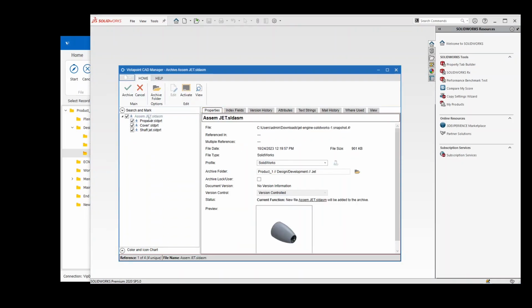Of course, it can read the SolidWorks file and find the files that are referenced in the assembly, but I can also add supporting files, any PDFs or reports, and I can specify those file types that I want to automatically or manually upload and add as a reference or remove a reference. So I can have all those files that I want to work with for this assembly.